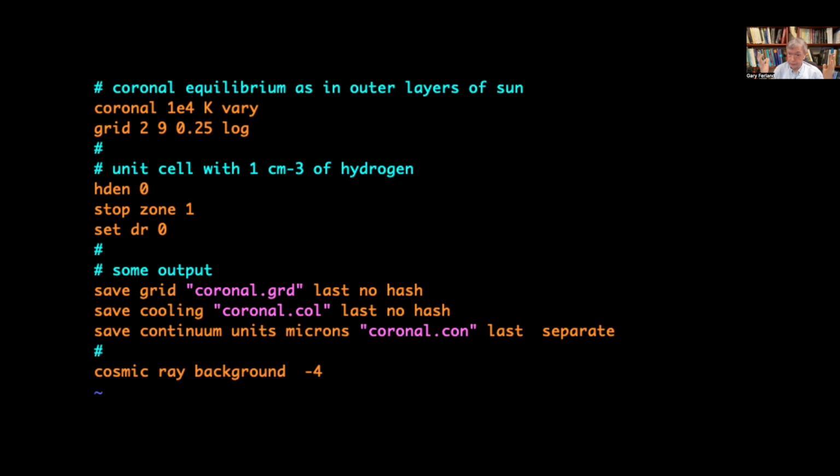So if you have a lot of save overview files, it will gather them together so it looks like you just had one single calculation that went through a lot of models in a sequential run. That gather in a large number of models can be the most expensive step because you could have hundreds of megabytes out there and trying to work all these files isn't cheap.